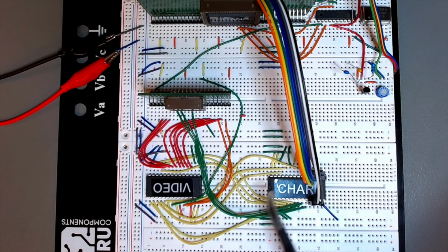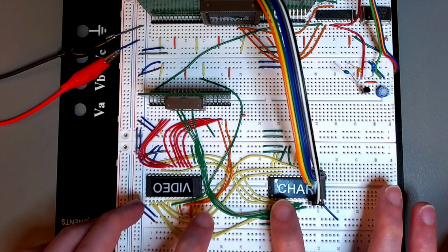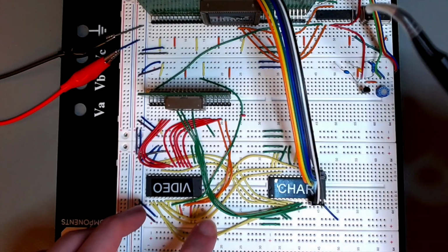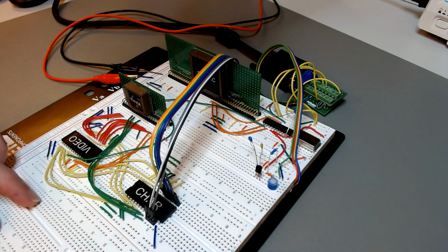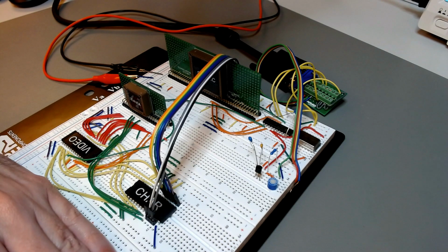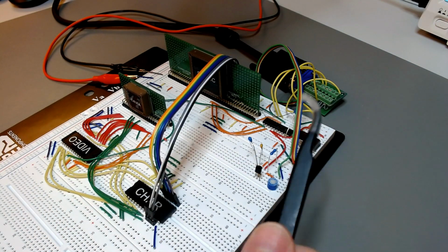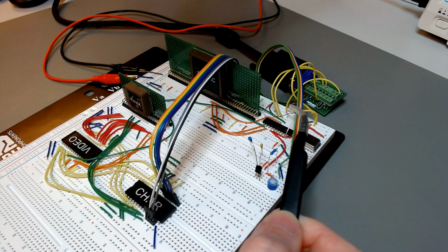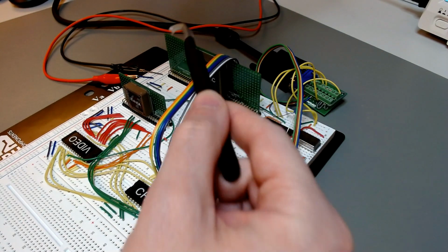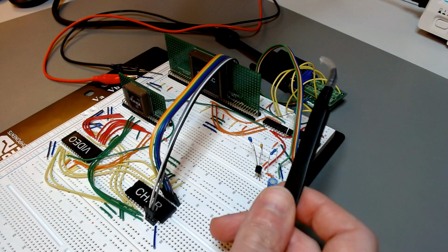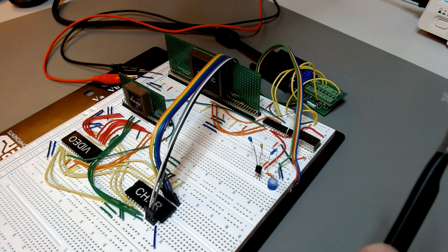Instead of the double EEPROMs, the final version of CERBERUS will have 2 dual-ported memories here, which means that the VGA circuitry can ignore what's happening on the other side of the dual-ported memories here. So that's why it's a completely autonomous system. When you turn on the computer, this kicks in, it does its own thing in a loop, and it will only stop when you turn the computer off.